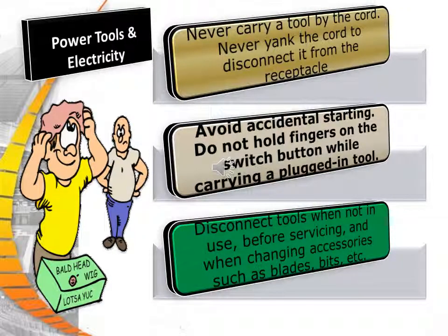Never carry a tool by the cord, and never yank a cord to disconnect it from a receptacle. Avoid accidental starting by not holding your fingers on the switch button when carrying a plugged-in tool. Disconnect the tools when not in use, before servicing, and when changing accessories such as blades or bits.